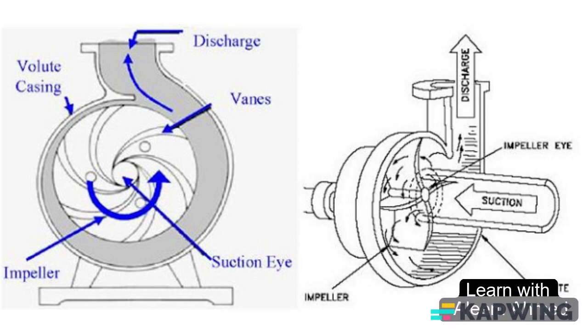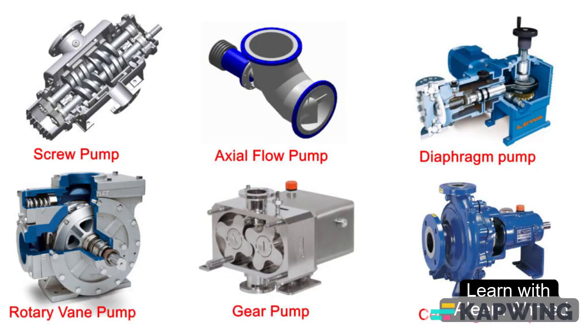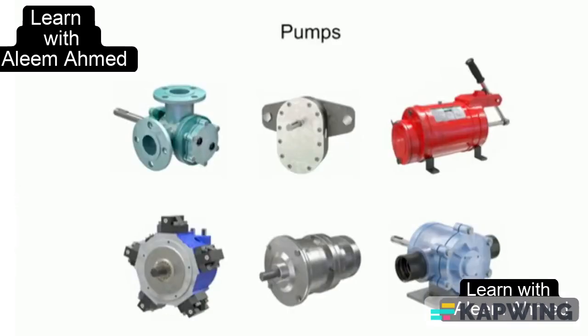The pumps are classified into two classes: positive displacement pumps and dynamic pumps. In positive displacement pumps, the fluid is directed into closed volume and the boundaries of the closed volume move in such a way that they expand or contract in order to receive and discharge the liquid. In dynamic pumps, there is no closed volume but there are rotating blades called impeller blades which input energy in the fluid. Many different types of pumps exist to assist fluid movement in a variety of systems.